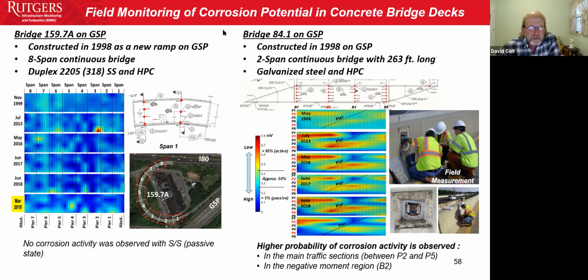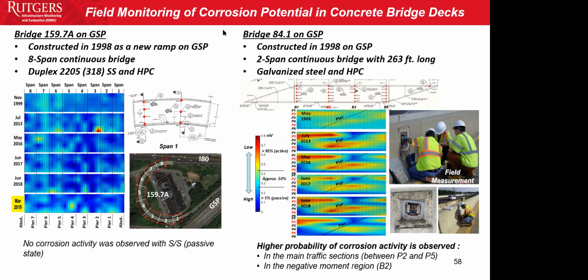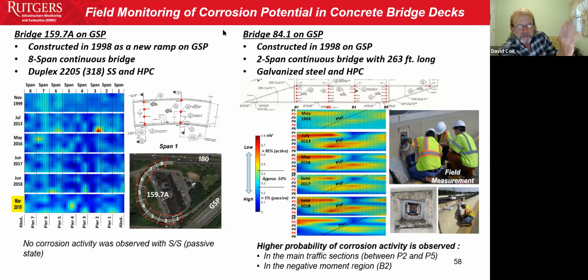Now, how did we select the alarm threshold? We did it purely based on observing the graphs. One thing we observed is that I might accelerate or decelerate degradation by changing crack size and chloride, meaning the graphs shift to the left or to the right. Every material is different, but for each material individually, we consistently see that when the degradation hits some point, it shifts.